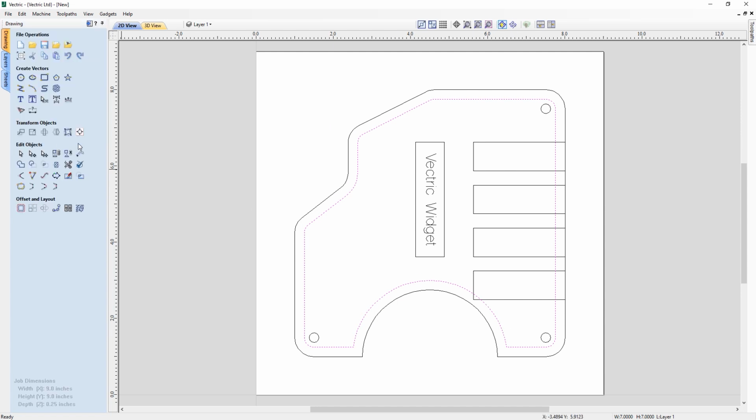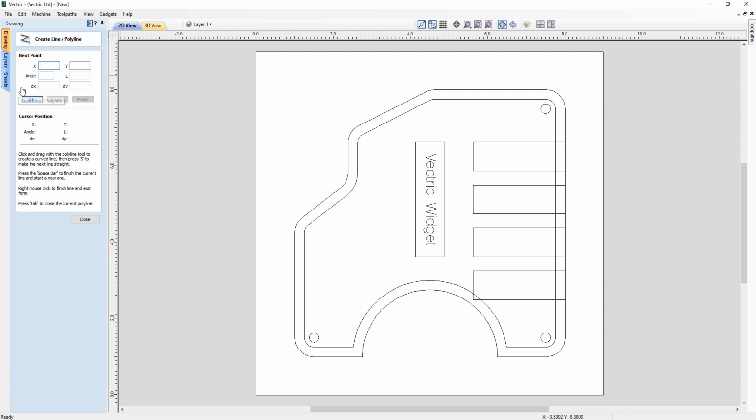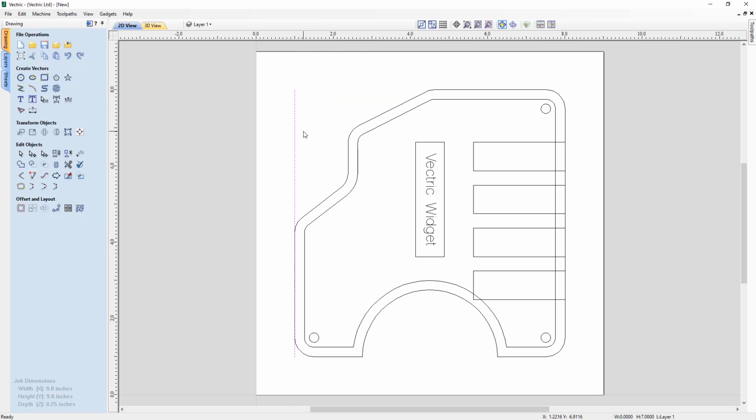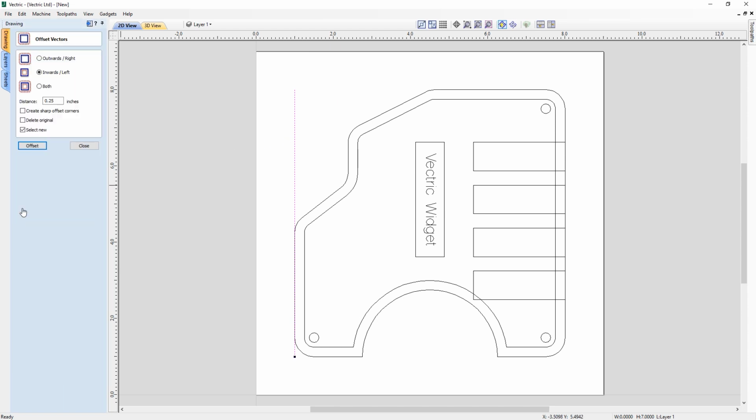Now, to create the left and right edges of this hatched area, we shall use a simple line drawn, which I will align with this side here, and just for convenience I will snap to the corner here, and then make it as tall as the project over here to create our vertical line. We want to offset this one 1 inch to the right.